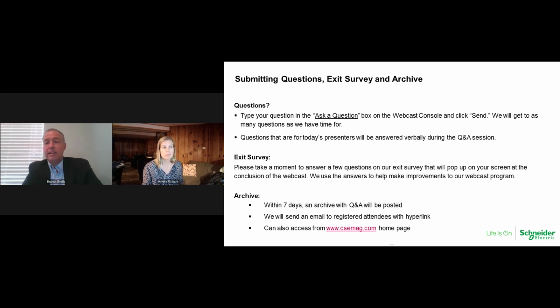Honestly, I hate seeing, for example, NEMA 3R. I know it's a common thing in our industry, and I'm in Texas. So I see people wanting to install their electrical equipment out in NEMA 3R enclosures, and I cringe a little bit because of the heat concerns.